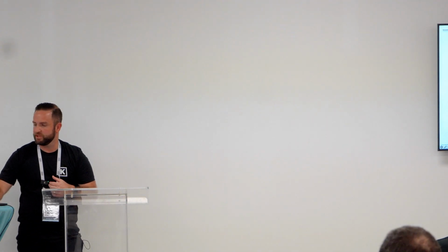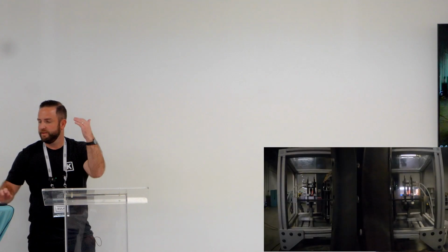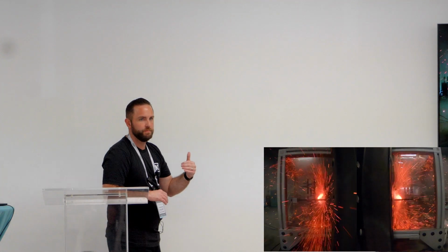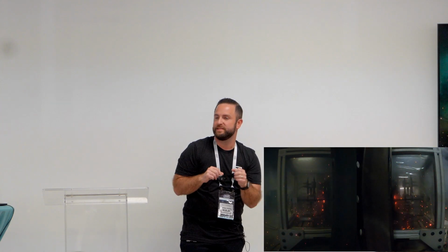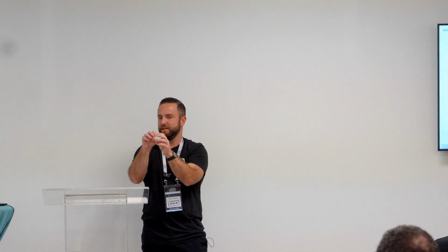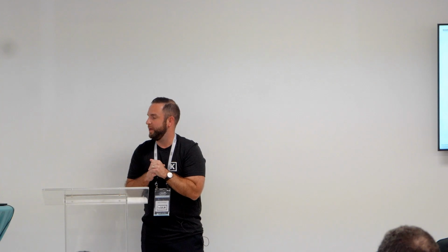So again, just to level set, I'm gonna replay a video from earlier. This is an example of a nail penetration experiment leading into thermal runaway. Nail penetration is a bit of an over-test to represent an internal short circuit. The idea is, you're puncturing a very targeted area of the cell that is then leading the cell to enter into thermal runaway from that initiation point. Fundamentally speaking, it's also a form of mechanical abuse because you're pushing all the layers into each other with the nail. So if you want to get into a debate on that, we certainly could do that over lunch today, of triggering methods and their merits.